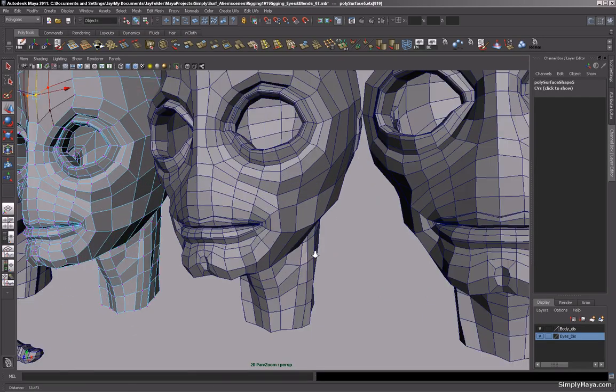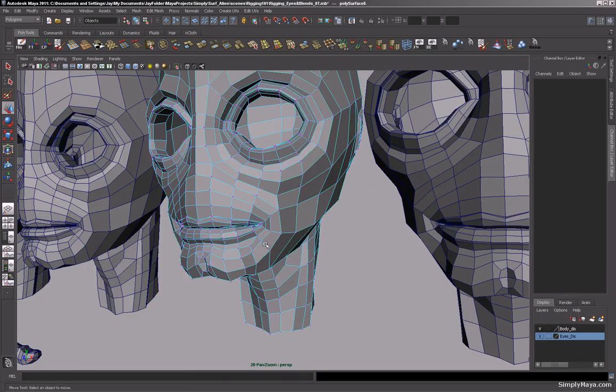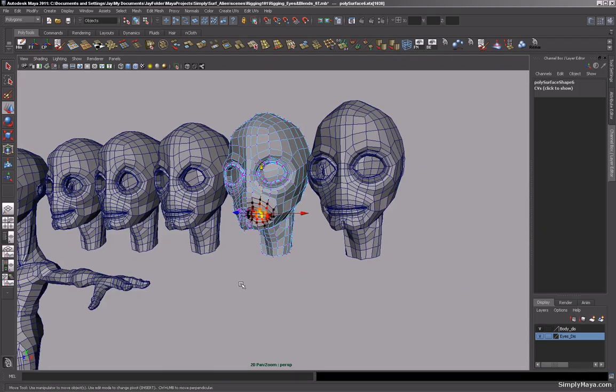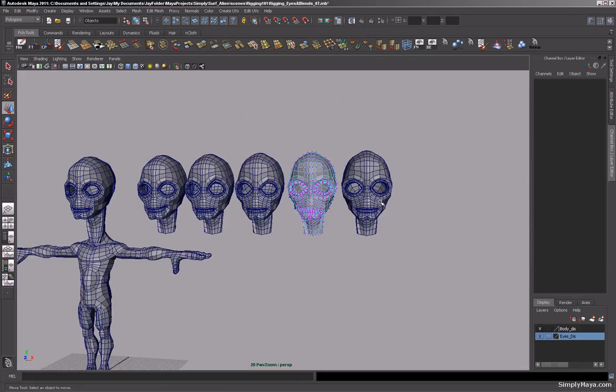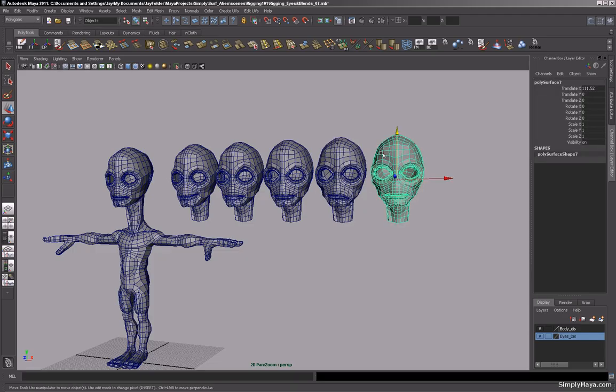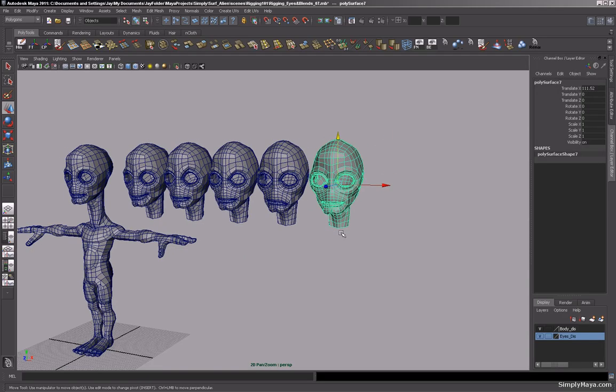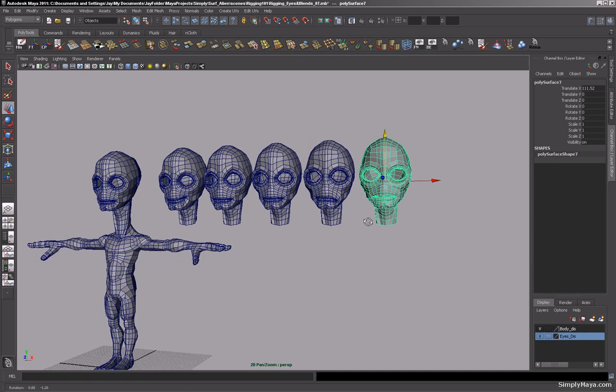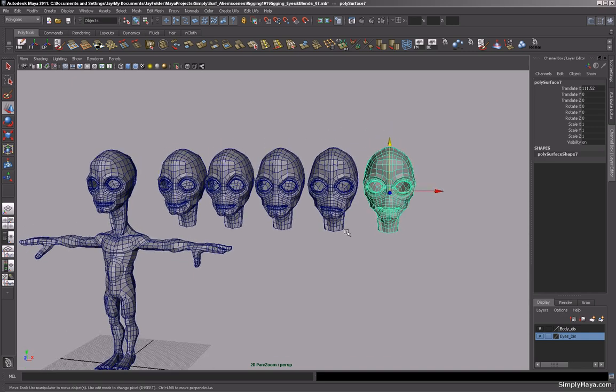And one more. We'll just do one more blend shape here, and we'll make this like a mouth frown type expression. Okay, like so. Now I'm not doing the end one, purely because what I was going to suggest is that you keep a spare one every time so you can create a new one. Otherwise you're going to have to keep going back, extracting the head. So always keep a default spare one so you can just keep duplicating along until you're finished with your blend shapes. Okay, so that's all good.